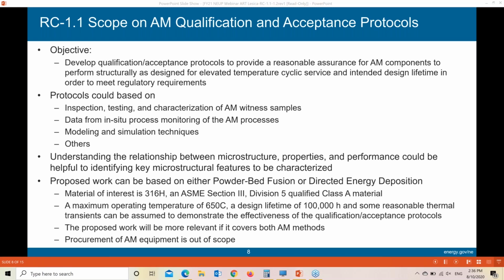For 1.2, as far as high temperature mechanical properties, graphite actually gets stronger, and the stiffness gets higher under radiation and at high temperatures. So really room temperature is going to be sufficient for any kind of mechanical testing.